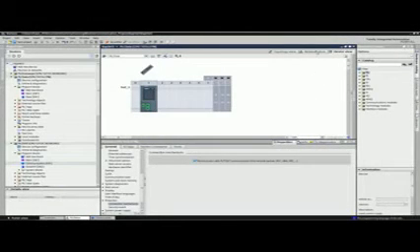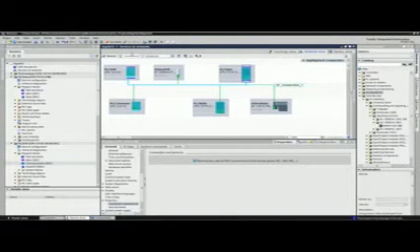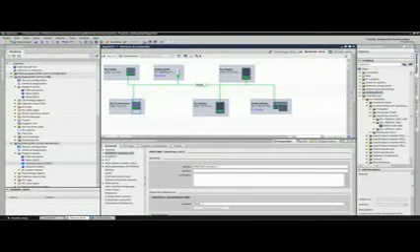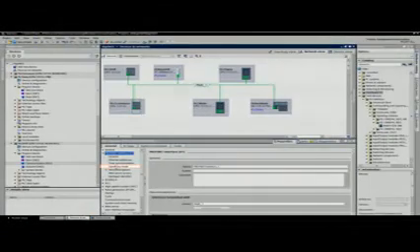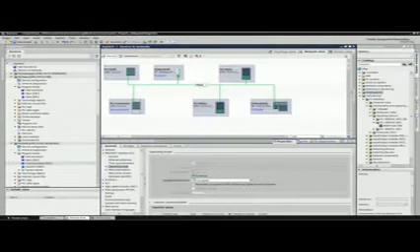The Profinet function iDevice, on the other hand, can function without any programming. To activate this function, you must first change the mode of the I/O controller to I/O device. In doing so, the I/O controller will become a Profinet I/O device. The next step is to assign a Profinet I/O controller to the resulting I/O device.